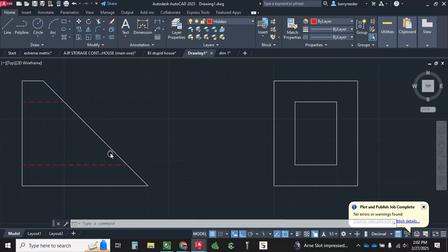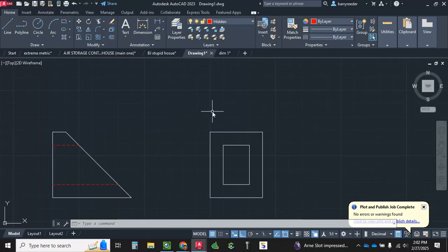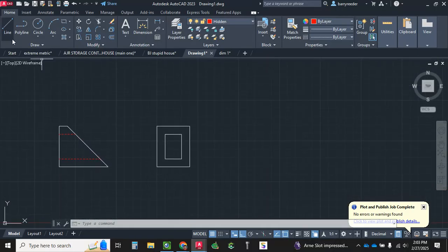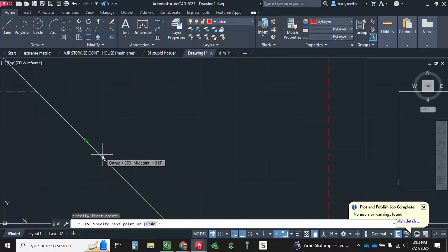Okay, now to draw an auxiliary view, you pick the view where that surface is a line. So the surface that we're talking about is right here. It's that surface there, but it's a line over here. So I'm going to come out here in space. If y'all want to pay attention here, I'm going to come out here in space and draw a line back to this. I do not want the center.